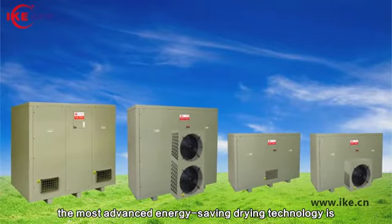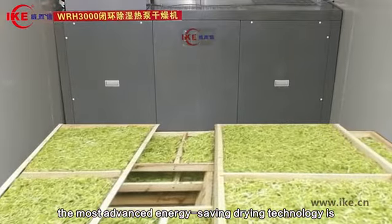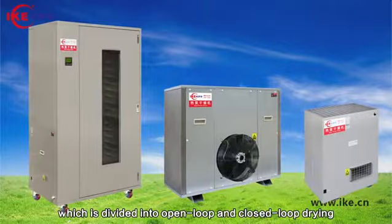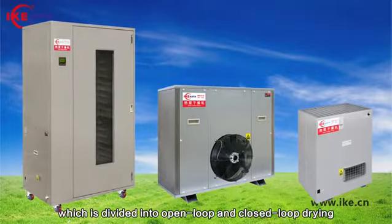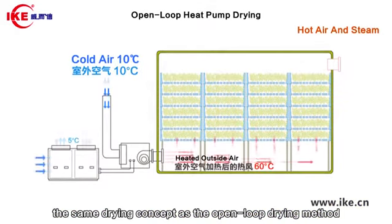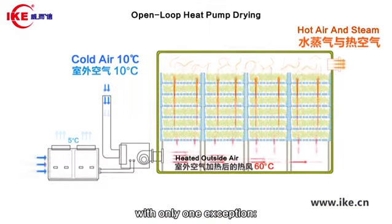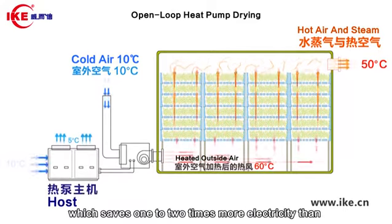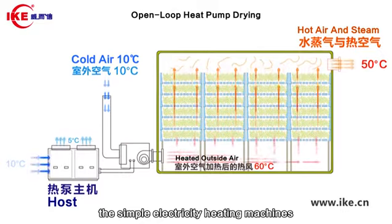At present, the most advanced energy-saving drying technology is heat pump drying, which is divided into open-loop and closed-loop drying. The open-loop heat pump drying method has the same drying concept as the open-loop drying method, with only one exception: the heating structure is replaced with the heat pump, which saves 1 to 2 times more electricity than the simple electricity heating machines.